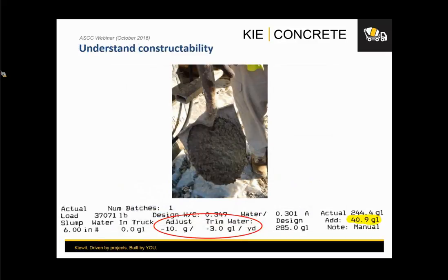And then something that is very common that you see, and many of you should be familiar with this, is withholding water in concrete production and trimming water. And those terms sometimes are used in different ways, but they mean the same, right? They mean basically they're avoiding putting all the water in the batch, right? So what happens when you have that issue, right? What happens now is that the concrete producer is inducing a more rapid slump loss in your concrete. And obviously that can accentuate with different properties of the materials, and with the temperature of the concrete and with the environment too.